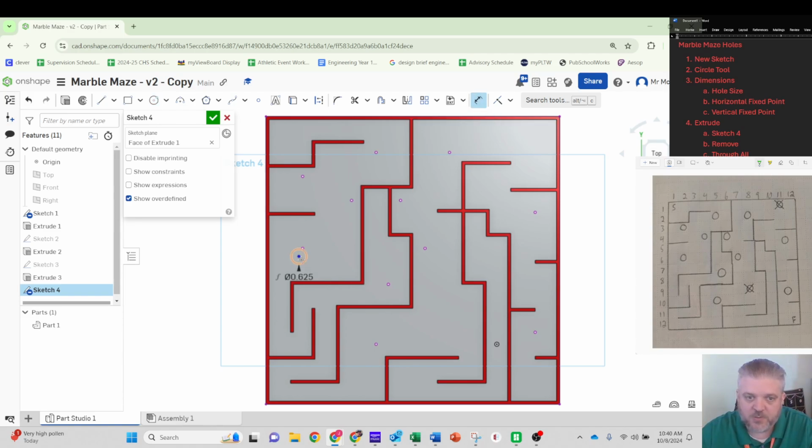Now I do my dimensions tool from the dot to the side, again 1.5 inches, and then from the center dot, we'll go to the top, because that's where I drew my 0 point line before, and, hard to see, but I'm at 5.5. Alright, so that circle is now in place. You notice the circle and the dot have gone black, so that means it's locked down.